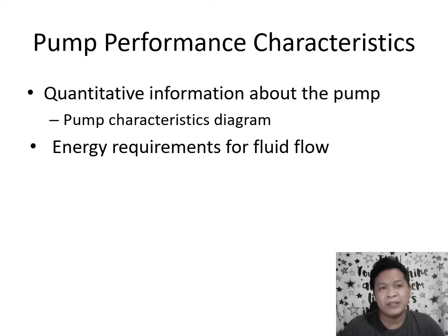And of course it has a maximum power it can output, a maximum suction height, a maximum discharge height, etc. And then maybe other characteristics such as fitness for use with varying viscosities of fluid and so on. And what is its most efficient point, no? Because when you design a system, say you have a house and you want to install a pump because you have a water tank, since the area lacks water, no?